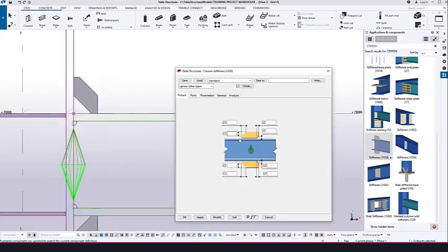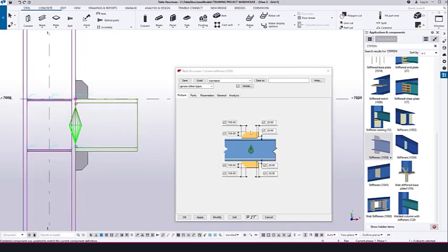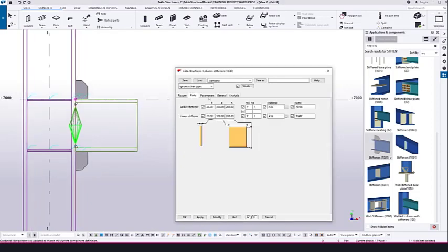Now go to the picture. Now I just change here, it is 100. Then here also I just make it 100. This one I just make it 20 for the welding gap, this gap, make it 20. And here also you can use Control C and Control V, and here also I just make it 100, then modify. Here it is fixed, you can see perfectly fixed. If you need more also, you can make that one, and it is okay.